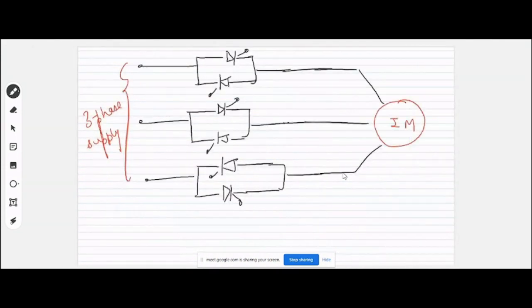We were discussing one of the concepts, how we can have this stator voltage control. If this is the supply voltage to us, what we can do is attach one voltage controller, an AC voltage controller, in between the motor and the supply. So by controlling the firing angles of the AC voltage controller, we can control the supply voltage to this motor. I guess it is very clear to the class, right? You already could have studied these AC thyristor voltage controllers, right?